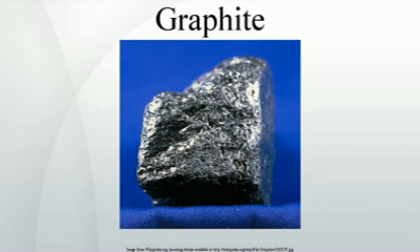Graphite recycling. The most common way of recycling graphite occurs when synthetic graphite electrodes are either manufactured and pieces are cut off, or lathe turnings are discarded, or the electrode, or other, are used all the way down to the electrode holder. A new electrode replaces the old one, but a sizable piece of the old electrode remains. This is crushed and sized, and the resulting graphite powder is mostly used to raise the carbon content of molten steel. Graphite-containing refractories are sometimes also recycled, but often not because of their graphite.